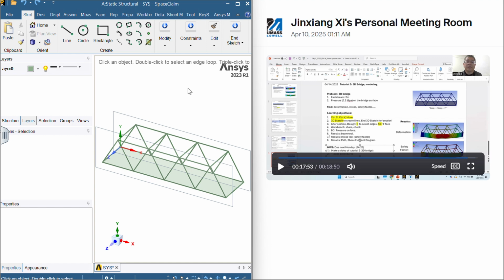Now I'm just gonna go into a little bit more depth on how to actually create the geometry. You can sort of see the steps here as well. So in our geometry, each beam is going to be 2 meters long. Once you've changed the unit to meters, you can draw out 2 meters here, make a triangle. So 2 meters here, 2 meters here, connect it, and then you can click escape.